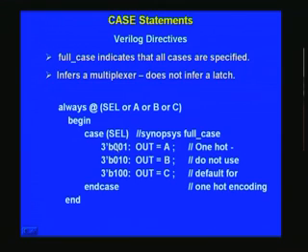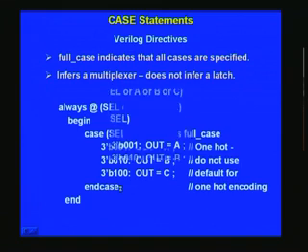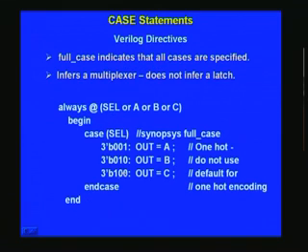If all the conditions are specified here, obviously they are not, and for 3 bits you have 8 possible states, and only 3 such states are considered here. What happens to the rest? When such a condition is encountered, will it be encountered? That is the first question we will have to put ourselves, and if it is encountered, we have to see remedial action for that.